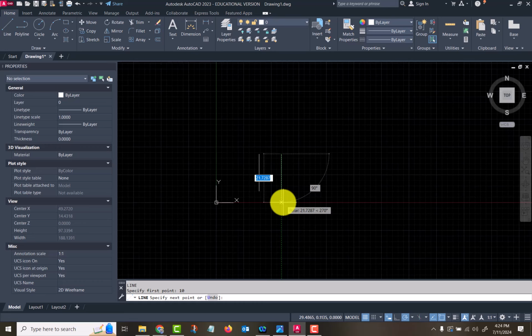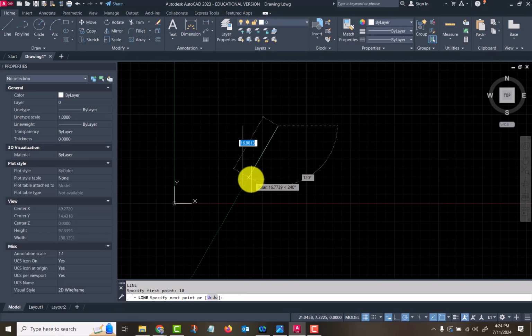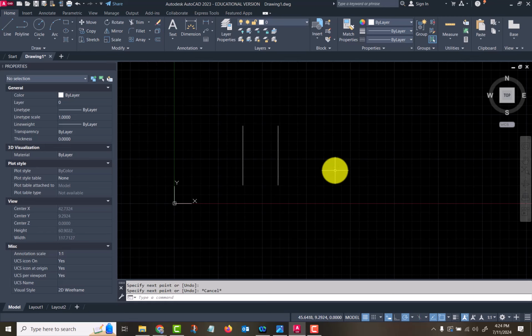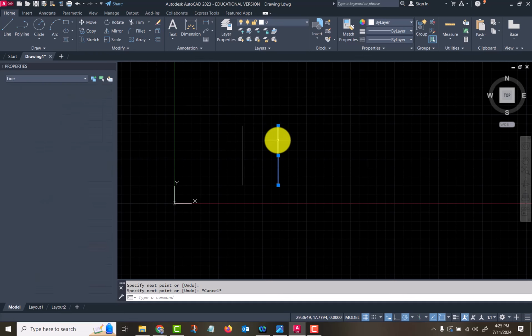And so now I'm coming down, and if I want to track off of the bottom of the existing object, I just hover my mouse over it and get the object snap, and just drag my mouse back to the right. Okay, so that's what we call object tracking, and you'll find as you're working through some of these things, it works out that way. Now then, let me take this one out.